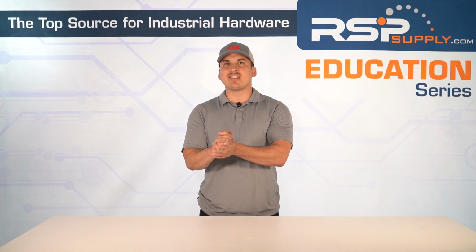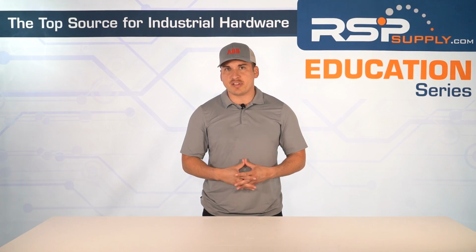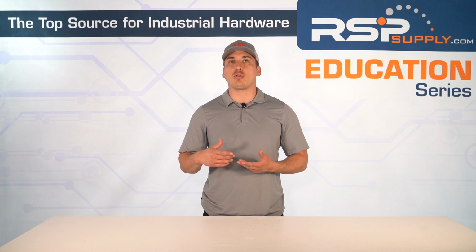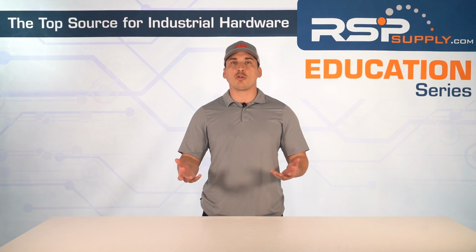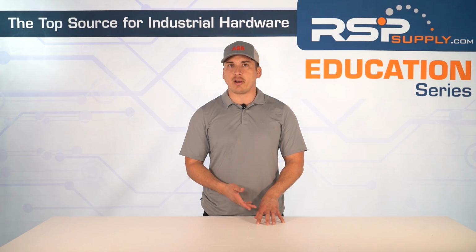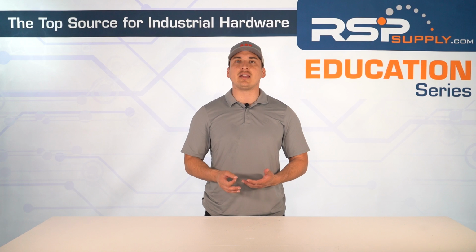To wrap up, capacitive, photoelectric, and ultrasonic proximity sensors each bring something different to the table. Capacitive sensors are great for detecting a wide range of materials, including liquids, non-metals. Photoelectric sensors handle longer distances and tricky surfaces like glass or shiny objects. And ultrasonic sensors, they're perfect when optical solutions fall short, especially in dusty, irregular, or transparent environments. Choosing the right sensor depends on what you're trying to detect, your environment, and how precise you need readings to be.